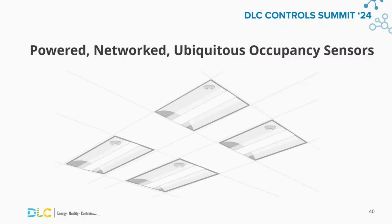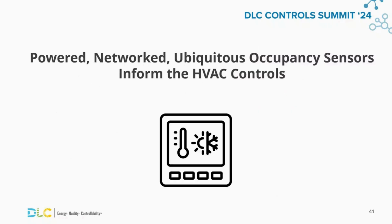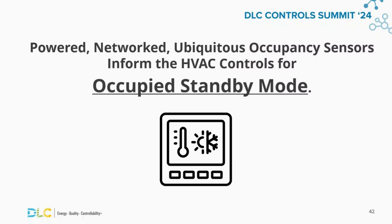An NLC system powers, networks, and distributes occupancy sensors evenly throughout an entire building. In sustainable buildings, signals from those occupancy sensors can inform the HVAC controls to relax the temperature set points by a few degrees in areas that happen to be unoccupied. Some buildings can also reduce the ventilation rate for additional energy savings. This is called occupied standby mode.